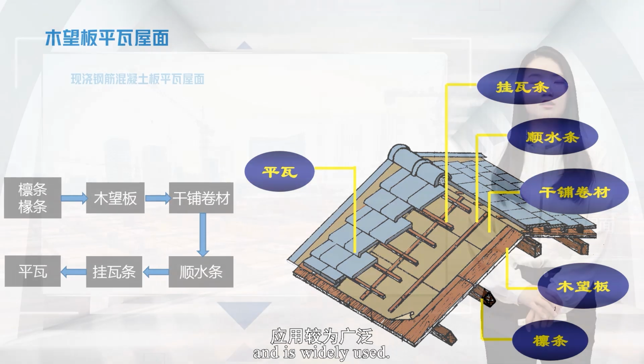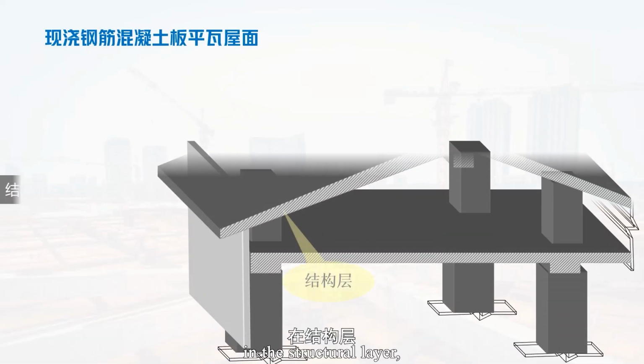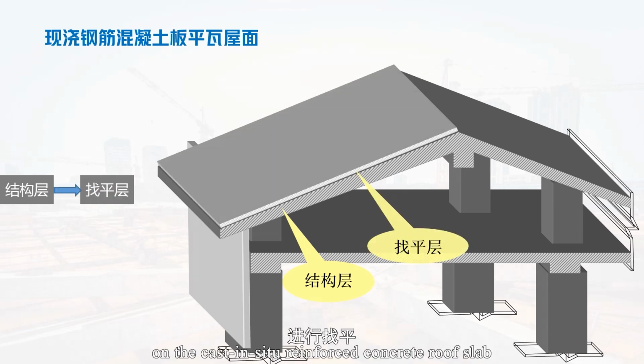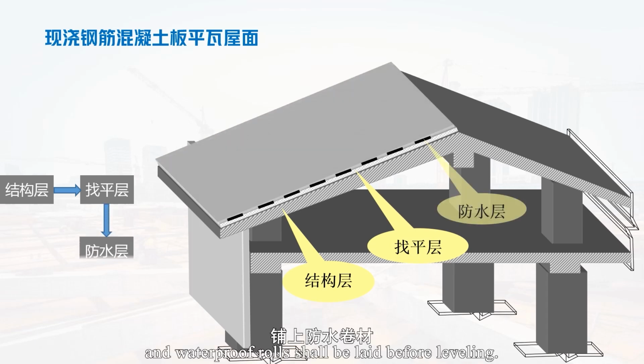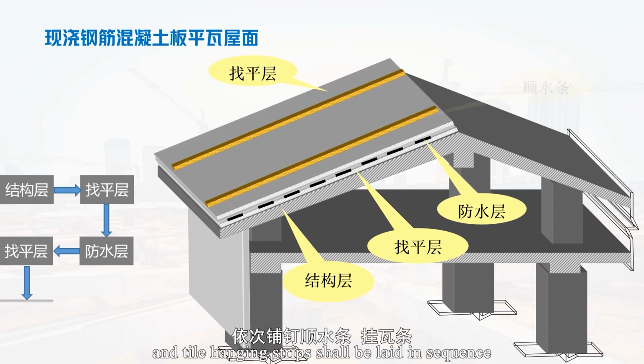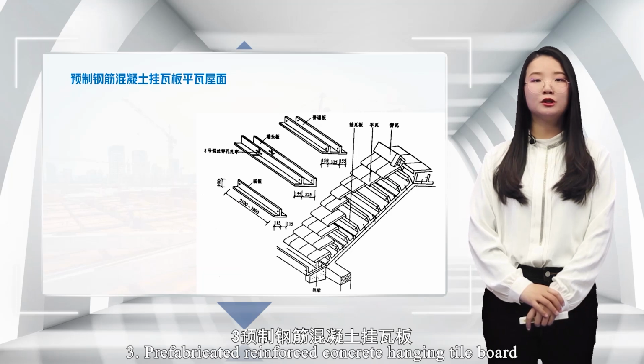is widely used. Second, cast-in-place reinforced concrete roof panel flat tile roof. In the structural layer, leveling shall be carried out on the cast-in-situ reinforced concrete roof slab, and waterproof rolls shall be laid before leveling. Then, water running strips and tile hanging strips shall be laid in sequence, or flat tiles shall be fixed with cement mortar.